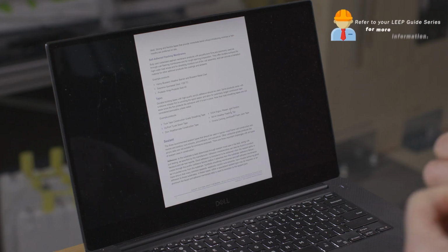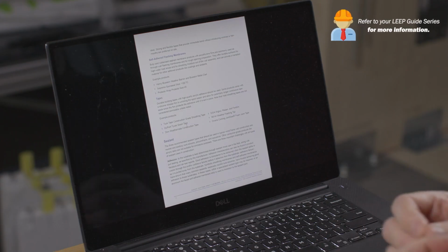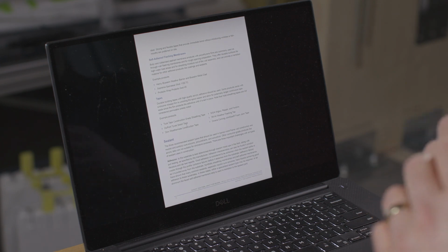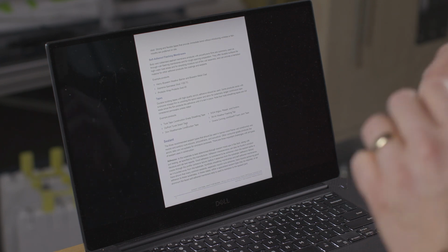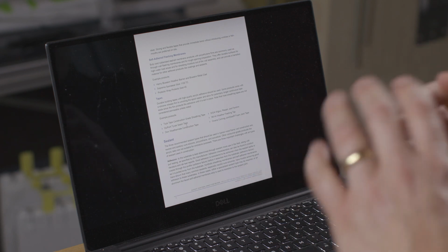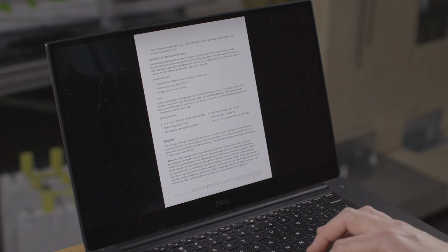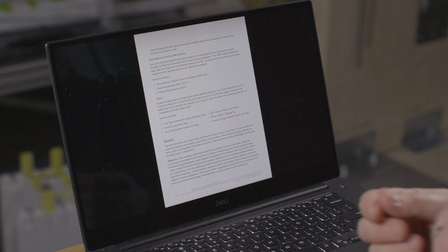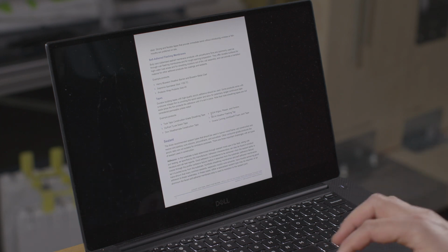As we get into something like a Dow Weathermate, Siga tapes, 3M all-weather tape, or Owens Corning tape, these are more flexible tapes with slightly better adhesion properties than other products, and they're often used for air barrier details where you need a bit more workability, flexibility, and even just a bit of robustness and adhesion. So lots of different tapes, and again, mock-ups and trying different components out there.